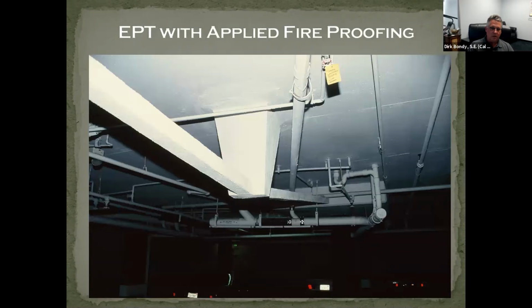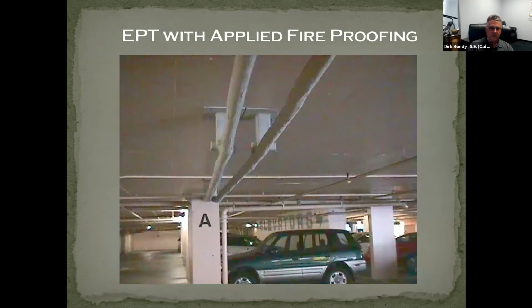This is what, when you do need to fireproof, this is what it can look like. This was a nice clean fireproofing of tendons and a king post. This is not very pretty. This was literally chicken wire wrapped. We use the section of the code that's for trusses. So the bottom chord of a truss, the way it gets fireproofed is the same way the post-tensioning gets fireproofed, with the same amount of vermiculite or concrete cover on the tendons, depending on the hours required for the fire rating.